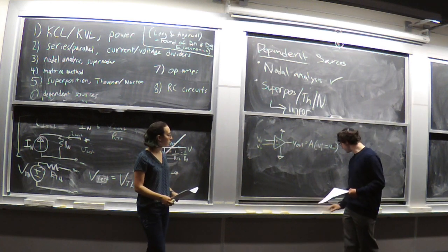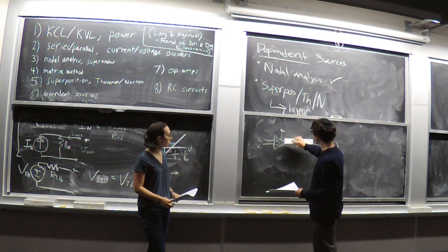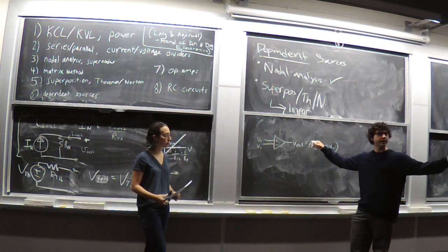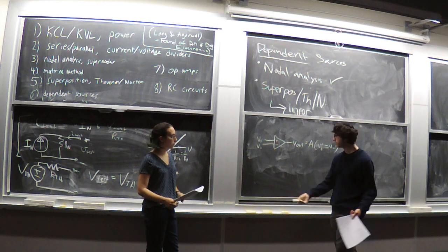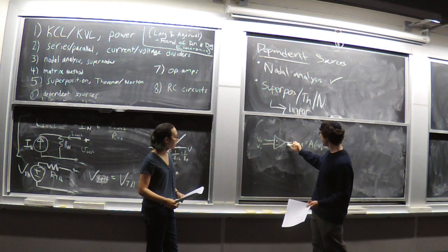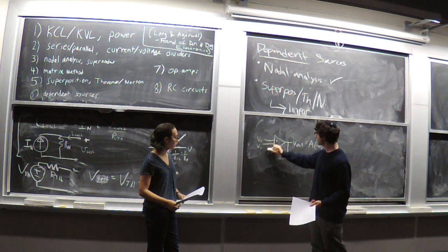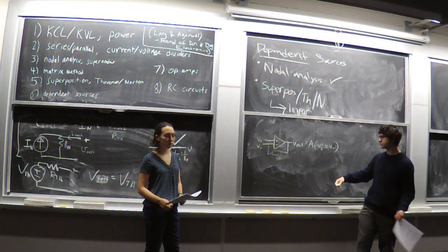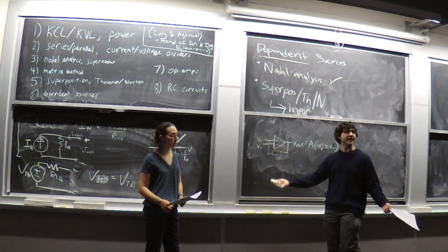And so often what we do is we employ what's called negative feedback. And the idea is that negative feedback sort of keeps an op-amp in check. It prevents it from growing unboundedly and capping out, or going down unboundedly and capping out, until it reaches a power rail. And so the idea is that we have some path. This can be anything. It can be a resistor. It can be some complicated network of resistors. It could just be a wire, whatever it is, back to V minus.